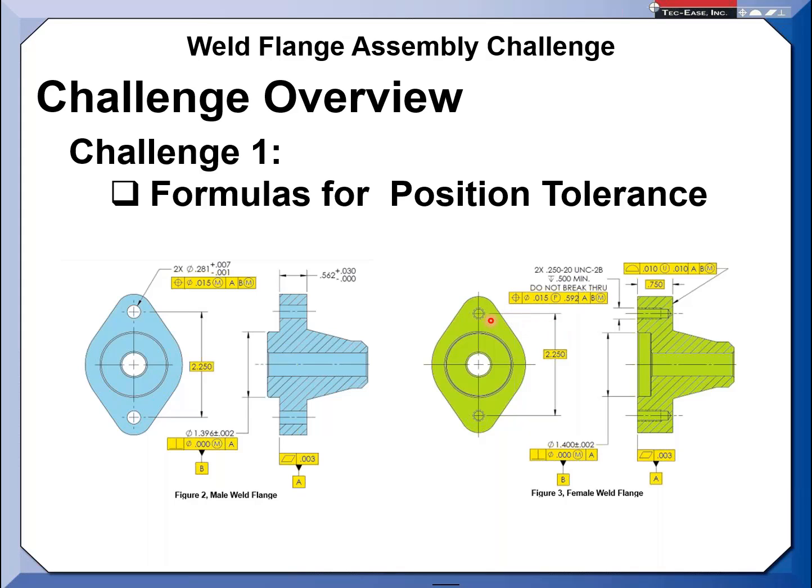When you put the bolt in here, the bolt is going to self-center. So some companies, can you put an M modifier here on a thread? Absolutely, the standard allows it. The M concept is about the feature departing from its MMC up to LMC, that as the hole gets bigger, I can allow it to move more.